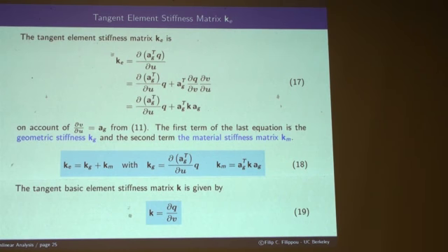But I can have geometric stiffness and no material stiffness. Think of a horizontal prestressed cable. With a high prestressing force here, I have stiffness in this direction. All of you guys know about this, right? If you stretch a cable and step on it, it's not going to collapse. There is a stiffness. All right. So the element stiffness is the sum of two contributions, geometric and material. This is the basic element stiffness K, and